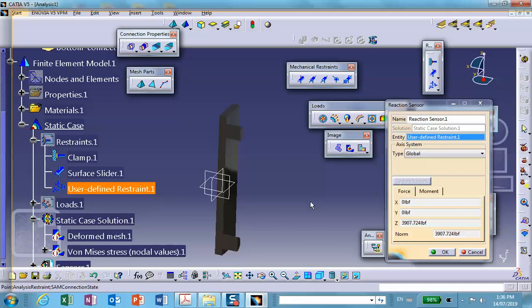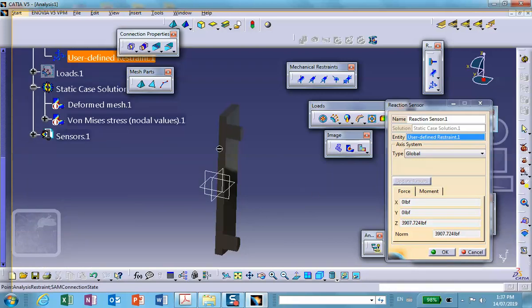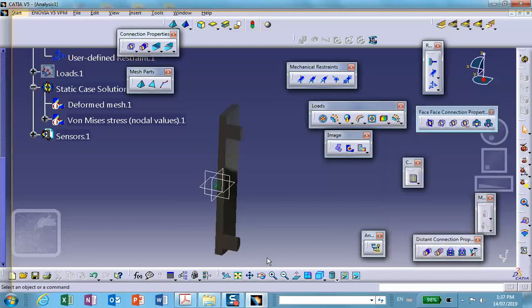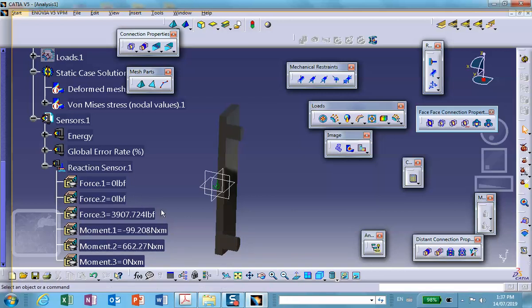Now the other thing is that, of course, I don't like it because that looks to be too large. You have to multiply it by 4, but that looks too large because I have absolutely no confidence in these numbers. Remember, I took a horrible mesh, did not even refine it. I took linear mesh without any refinement. So if the mesh was acceptable, then the total load to do this would be 4 times this number, and that's what you write in your exam paper. Now, don't cancel this, because if you cancel it, there's no way for us to know where you got this number. Say OK, and when you save it, this information is going to be saved so that we can check and find out where you got your number from.